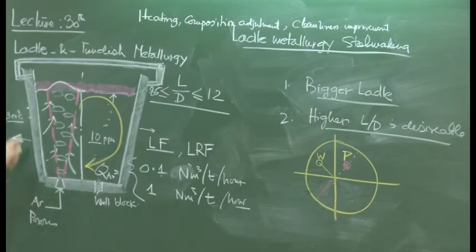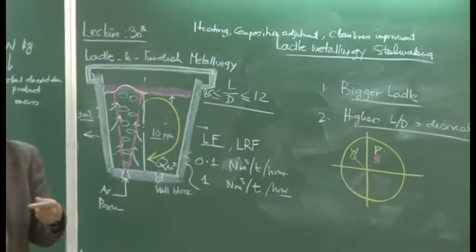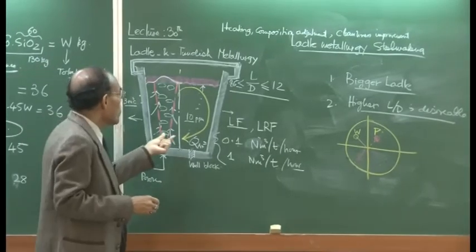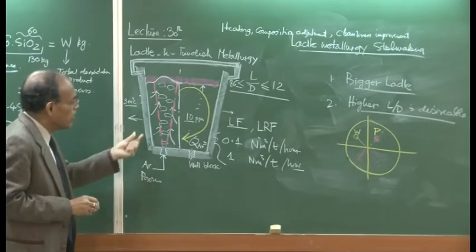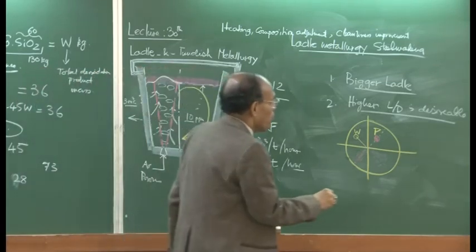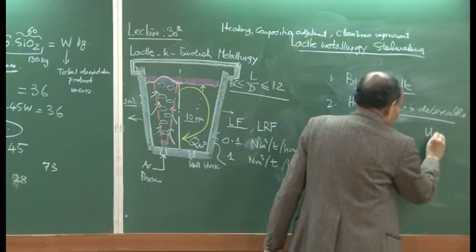We have, for example, the intensity of flow, which is very important, because the intensity of flow determines at what rate alloys are going to melt and dissolve, since these are all convection controlled processes. So, an idea of the flow intensity is important, and there are two velocity scales people normally use.